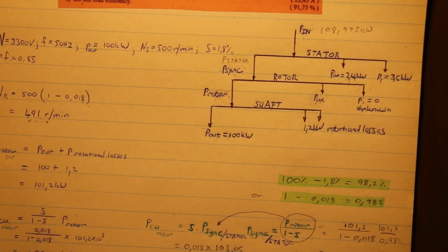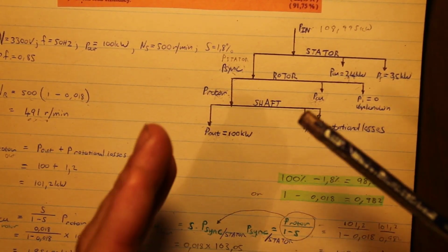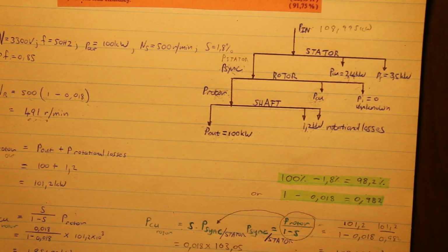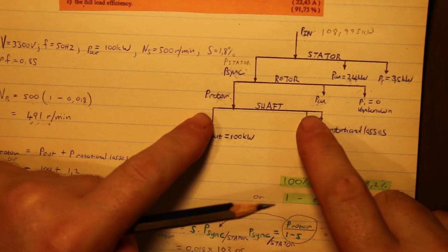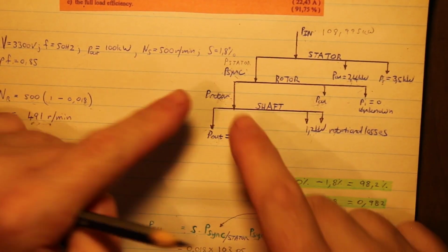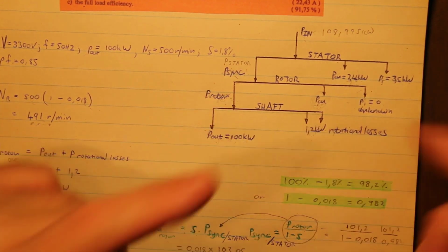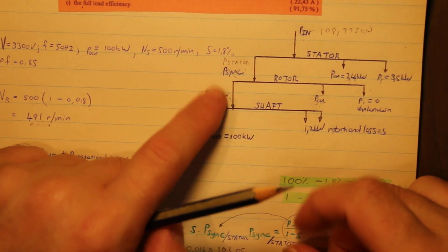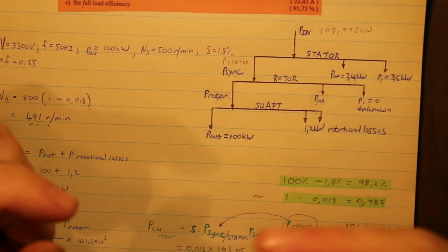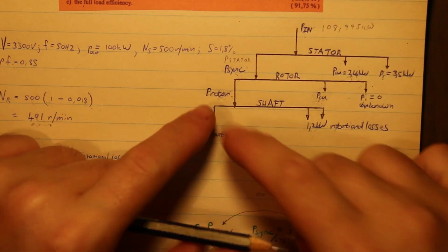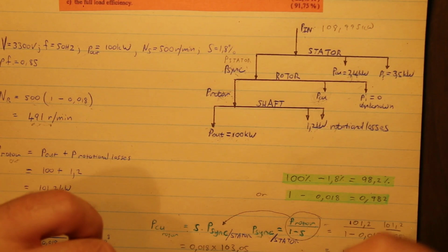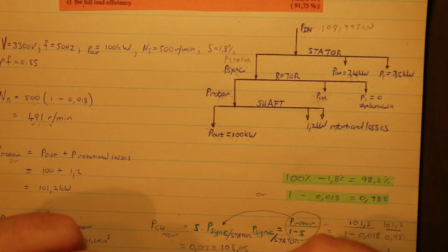So I hope that illustrates how to use the diagram for the problem. So you just plug in the information that you get on the diagram, and then remember, be able to visualize what the shaft is. The shaft is physically fixed to the rotor. Okay, the shaft has its friction and windage losses. The rotor interacts with the stator rotating magnetic field. It can't move at the same speed as the synchronous speed because of slip. And yeah, so hopefully that helps you guys out.